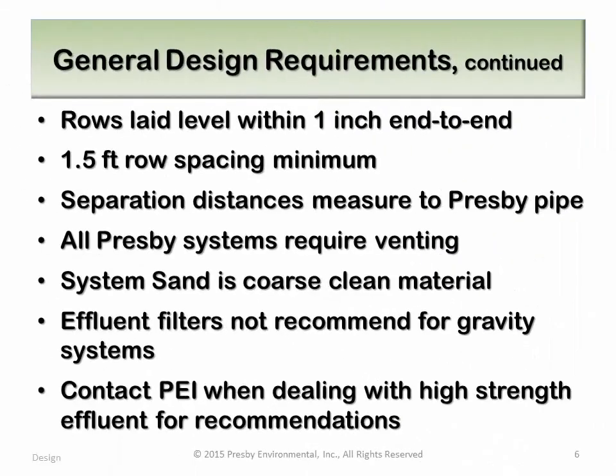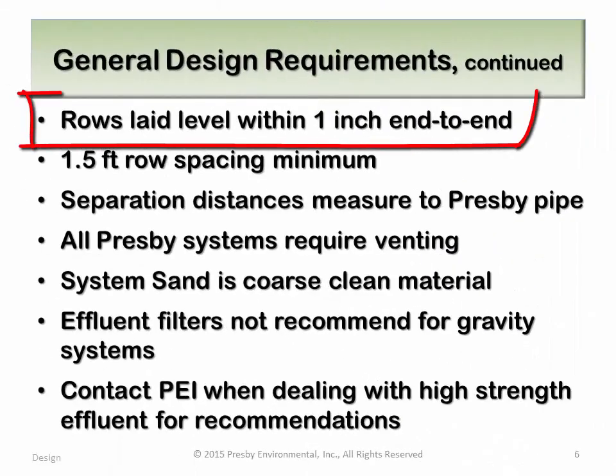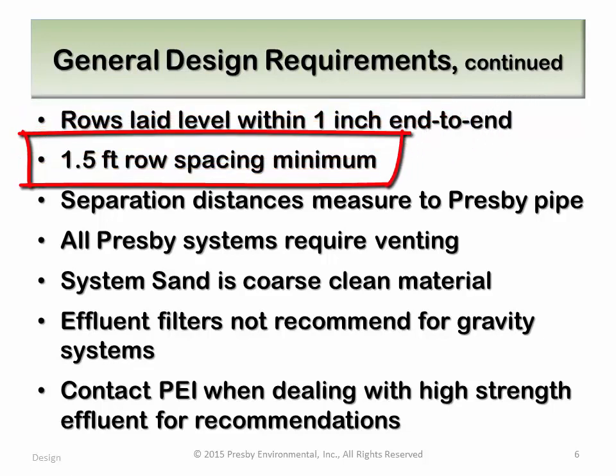Continuing with our general design requirements, all Presby rows must be laid level to within 1 inch end to end, regardless of the row's length. The minimum center-to-center row spacing, as we mentioned earlier, is 1.5 feet. The designer is free to increase this at their discretion. However, you will use more system sand than would be required at the 1.5 foot spacing.